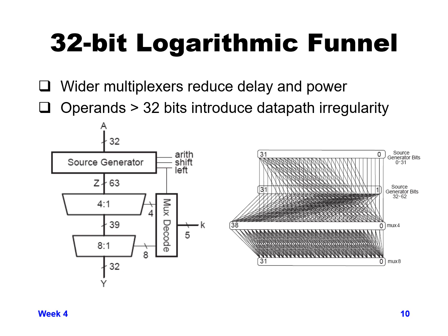And then the second set of multiplexers will be an 8-to-1 set where we'll shift by any value between 0 and 7. So with a multiple of 8 up to 24, and then 0 to 7 individually after that, we can get any shift between 0 and 31 through our shifter.